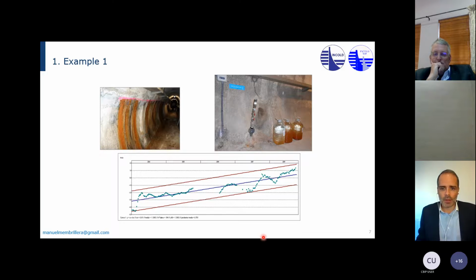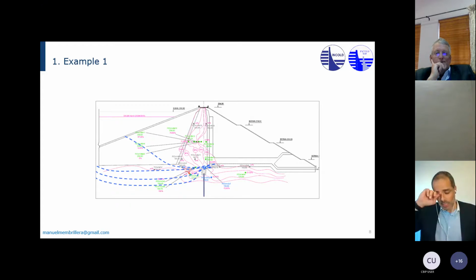And so the problem with this dam, and by the way, last year we had another sinkhole at the right margin. So again, the piezometers at the right, close to the right abutment, piezometers downstream and upstream of the core give you almost the same pressure. So there's no energy, no gradient loss in the foundation. And last year we found another sinkhole here at the upstream shoulder, but really caused by internal erosion down here.